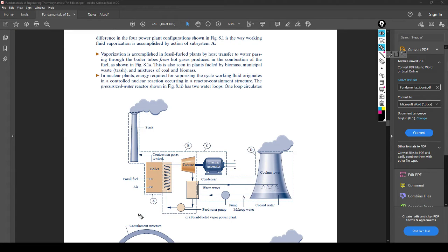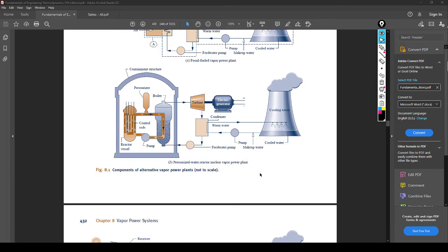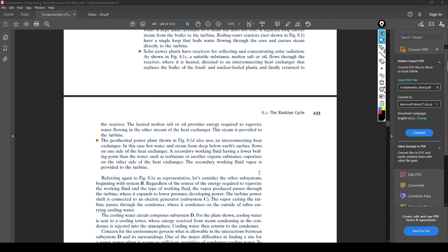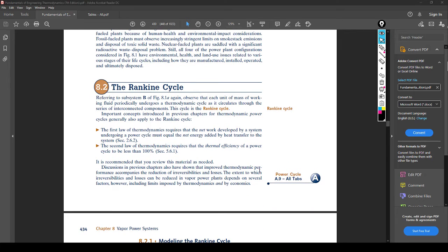So obviously, due to losses and a bunch of other things, like turbine work and condenser heat transfer, heat's going to leave. We're going to lose work due to friction and a bunch of other things. The thermal efficiency of this power plant is not ever going to be 1. Most cycles, for Rankine, I don't want to be wrong about this, but I'm pretty sure they end up in the, I want to say 40. I know mid 30s to mid 50s is probably where you would expect.